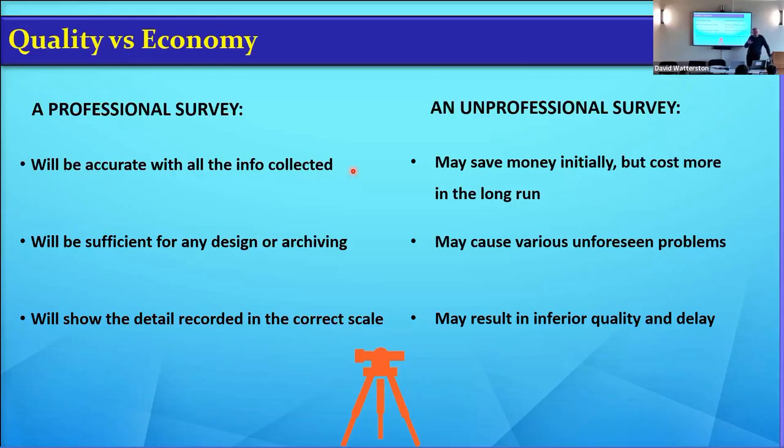So you would buy the Ordnance Survey digital data, which is the line work, and you might get the odd few levels as well for about 20, 30, 40 quid, depends on the size of your site. And then you can go into Google and get the Google image, which is not great when you zoom right in, but if you slap that on top of it and scale it up, then what Google tells you where the boundaries are can match the Ordnance Survey, which gives you a good idea for going out and doing your preliminary design.